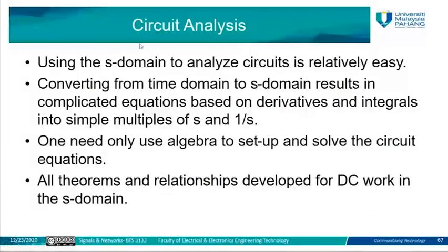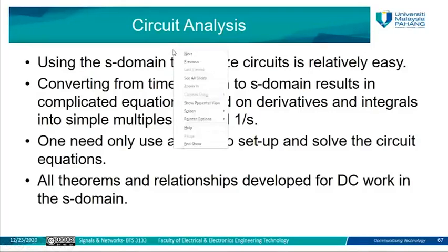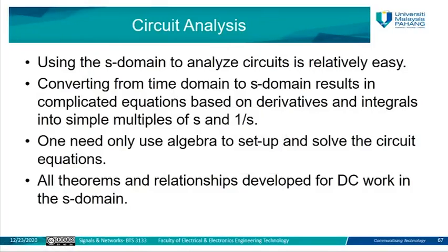So we are going to use this Laplace transform to solve or to analyze the electric circuit. In order to do that, we first need to convert all elements or all components in the circuit from the time domain to the frequency domain, according to the table that we shared before. That applies to components like resistor, capacitor, inductor, and also the voltage or current source. Then we are going to use algebra to set up and solve the circuit equations.